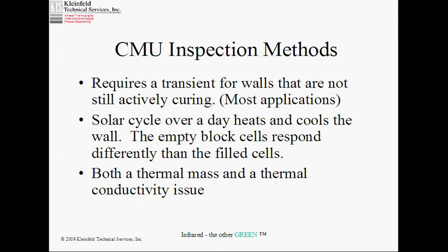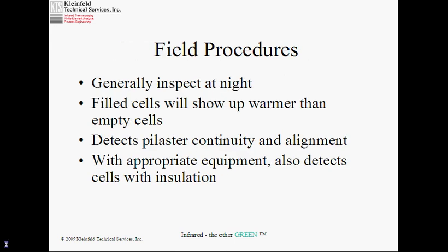This generally requires a transient, and the transient of choice, again, is day-night solar loading changes. If the grout in the pilasters is still generating heat because it's curing, you can see that signature, but often that's not the case. So unless you're actively following the pours day by day, not the way to go.